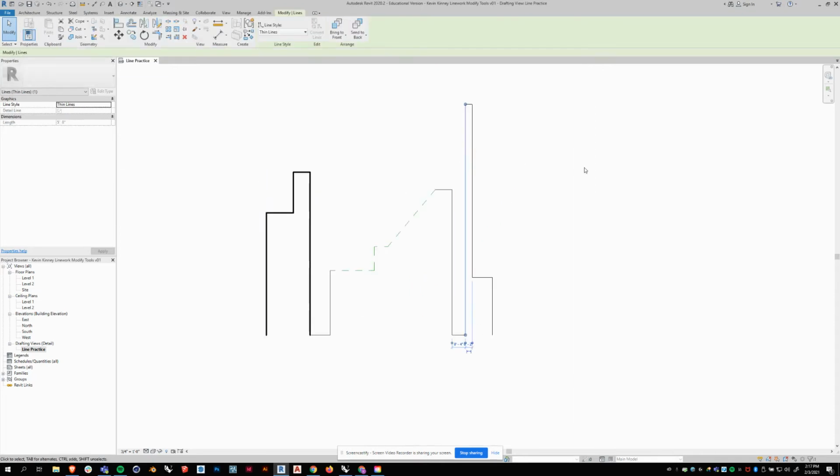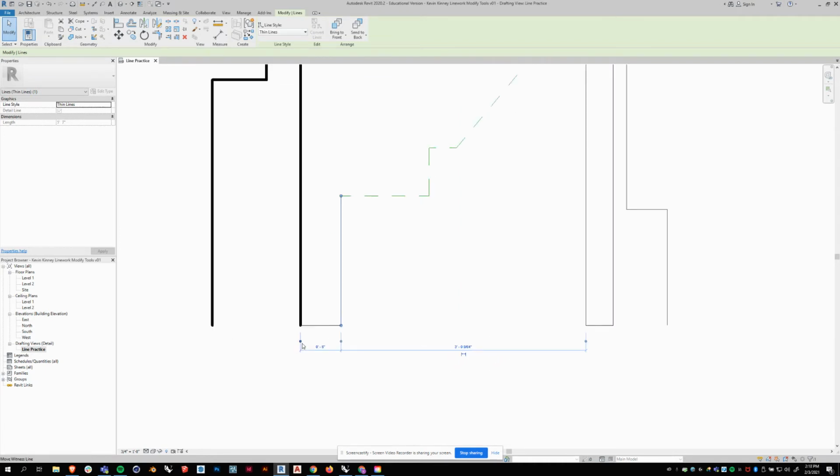So any sort of line you select, you're always going to get these temporary dimensions, as we've talked about before. And I can always move this temporary dimension by holding down with my left mouse button this little button, maybe move it over to this line. And I can say, hey, this needs to be 1'6" from there. It's going to move over a little bit.